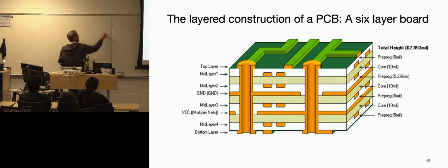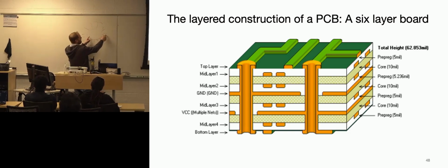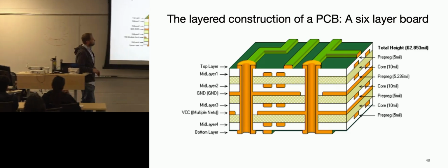Okay, so you have a ring, and this is going to be your hole. So this is the thing that's drilled, but this is all copper as well. And they're saying, I need to have enough copper here so that if I'm off, say I'm trying to do alignment, and my next hole is over here, off by a little bit, I can guarantee all these things will align. It's giving them a little buffer room so that they can be misaligned. So that's why these annular rings can be pretty large. Does that make sense?